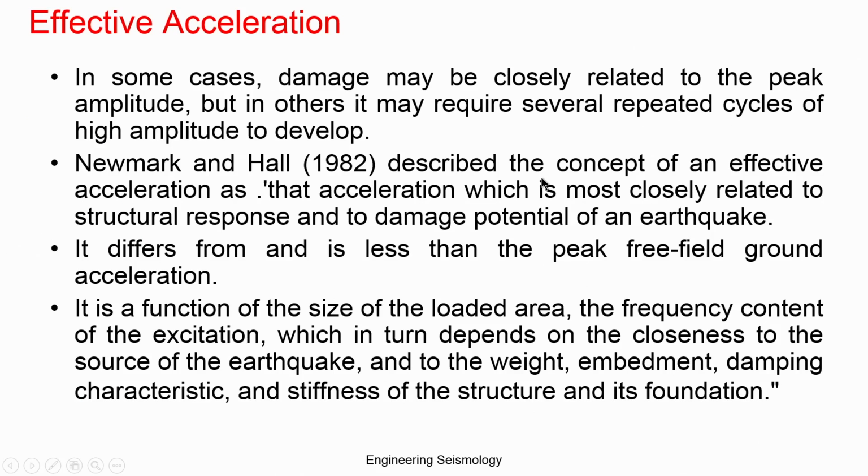Dobry and others in 1982 described the concept of effective acceleration as that acceleration which is most closely related to the structural response and damage potential of an earthquake. It differs from, and is less than, the peak free field ground acceleration or peak horizontal acceleration.